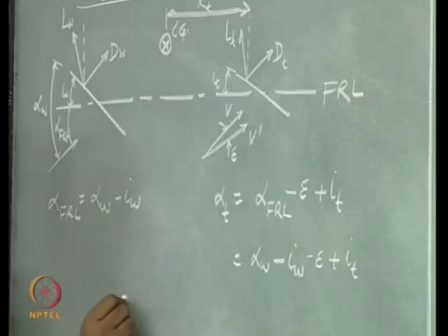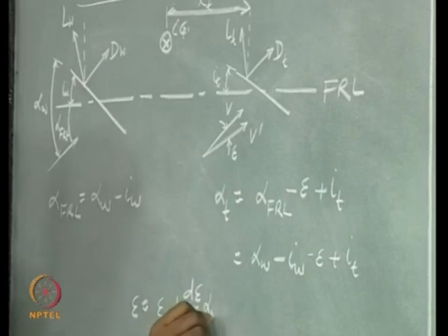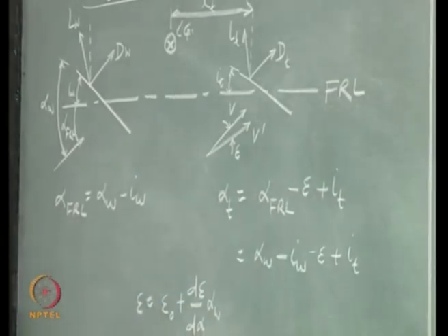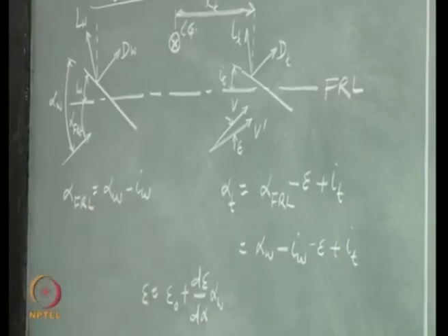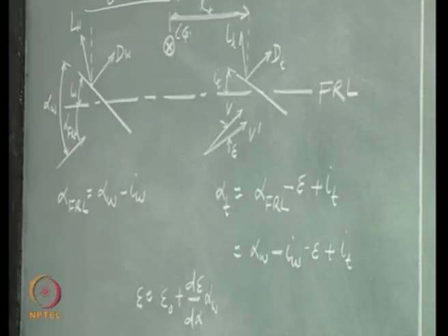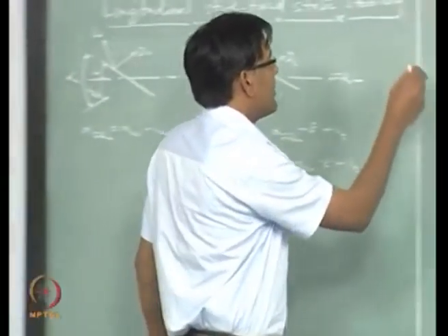We also said that this epsilon has two components, right. So the downwards angle itself is changing with angle of attack of the wing, right, plus this epsilon when the wing is at 0 angle of attack. Okay. So, coming down to what we achieved by adding a tail.